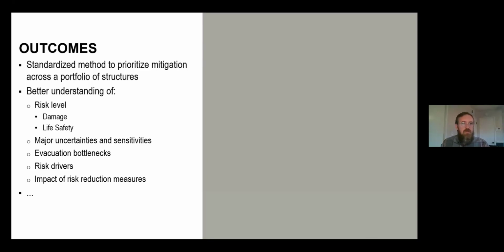It's really a great tool to better understand risk, right? Both in damages and life risk. You can also understand major uncertainties and sensitivities in the data and recognize evacuation bottlenecks. It's important to be able to understand risk drivers in your overall risk assessment if you can quantify the difference between a gate failure versus a dam failure, for example. And then you can look at the impact of risk reduction measures.